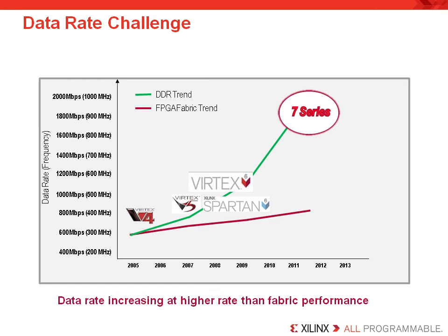Now, as this graph highlights, FPGA fabric speeds have trouble keeping up with memory bandwidth speeds. To meet system performance, designers need a mixture of soft IP that allows designers flexibility and hard, fixed technology that supports the highest memory controller performance.